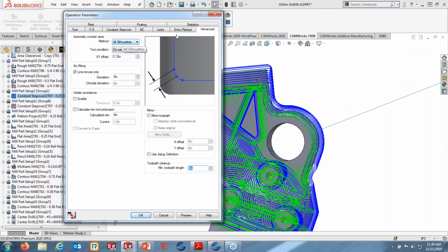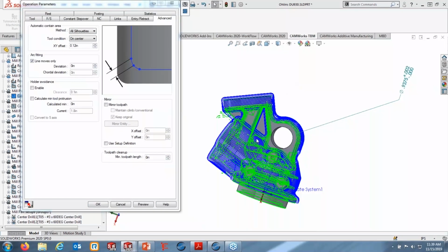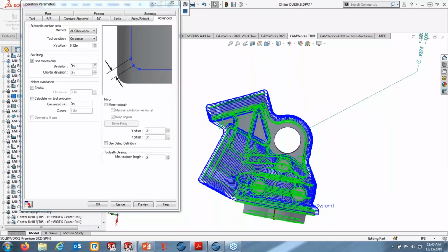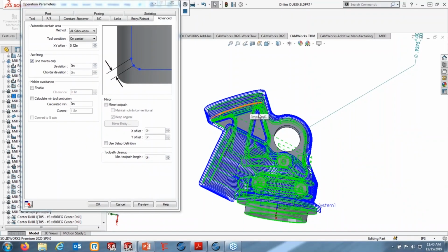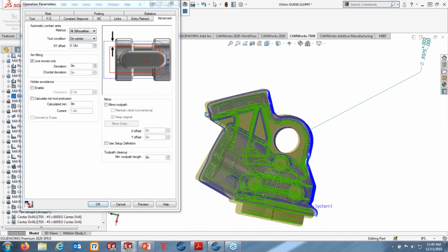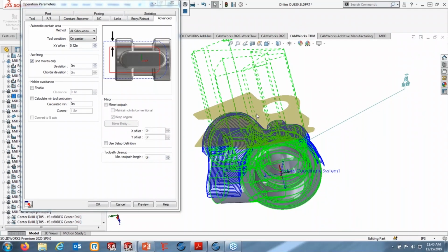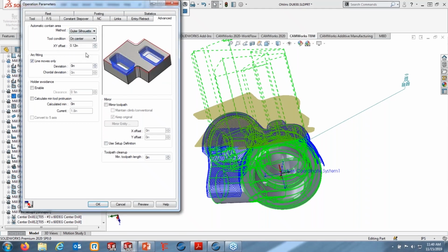I'm in my advanced 3-axis toolpath here, going and doing some finishing work over here. Why is the toolpath staying away from this boundary? Why is it not going any further past? Well, I've now got this yellow reference to say, okay, the tool is going to drop in this hole, or it's going to stay away from this hole, depending on what I set it to.